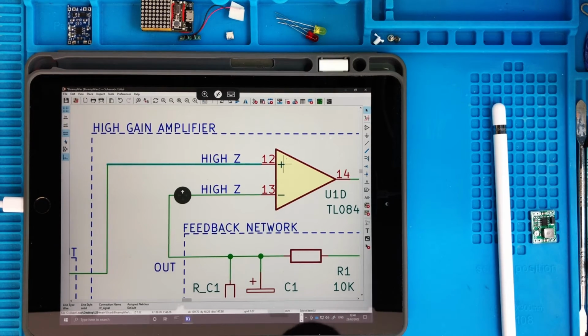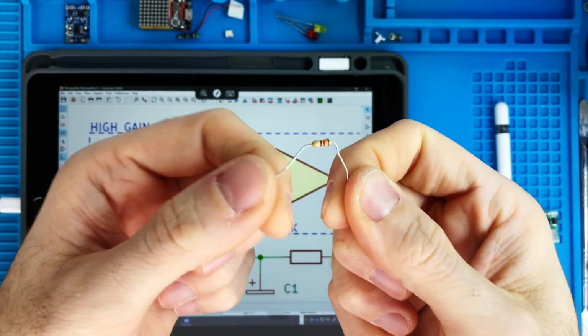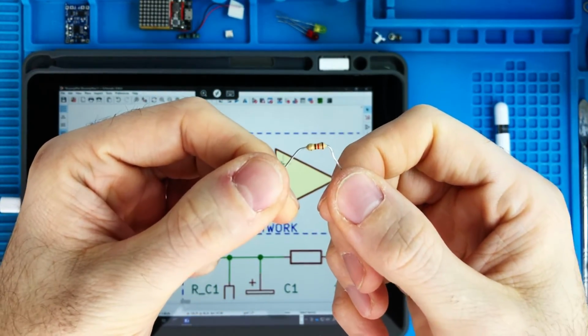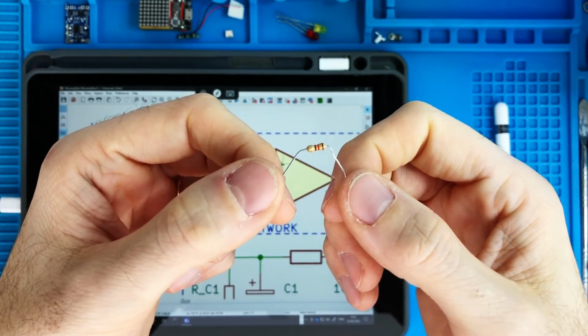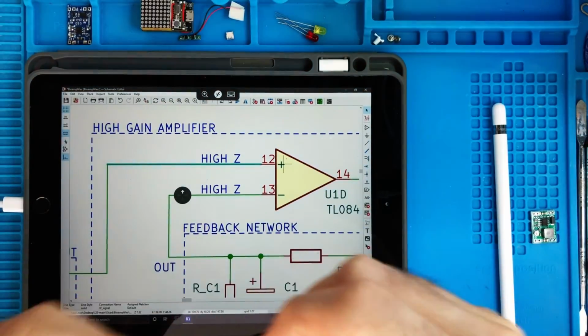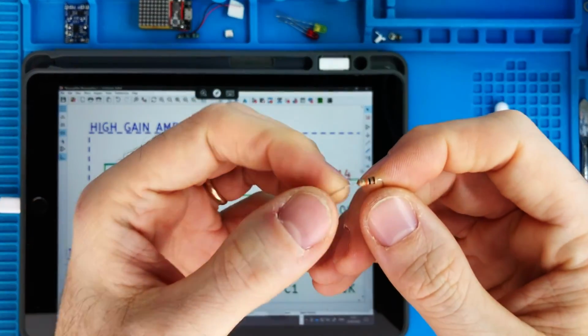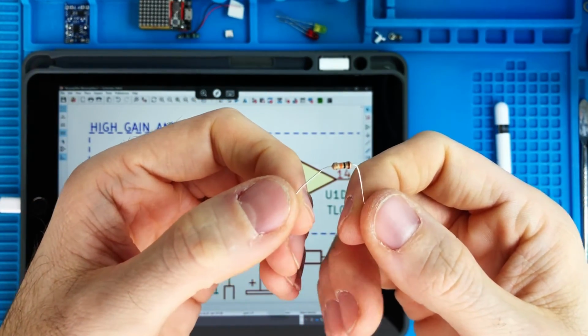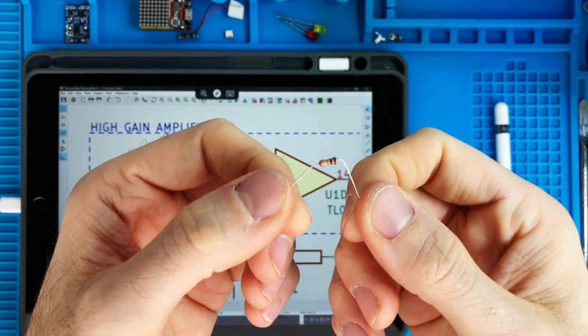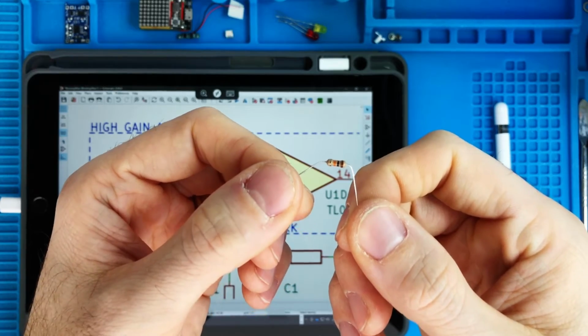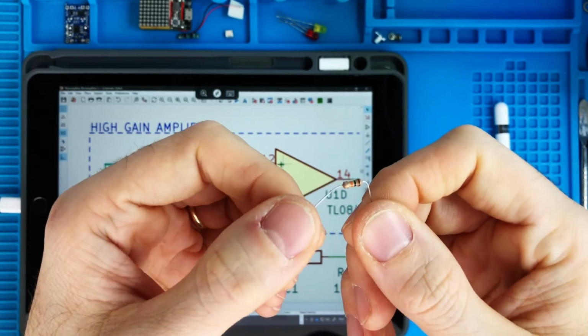So if you remember the trick I did by measuring the resistor and touching this with my hands, the impedance of a resistor of about 10 kilohms was already affected by putting 300 or 500 kilohms in parallel to this.